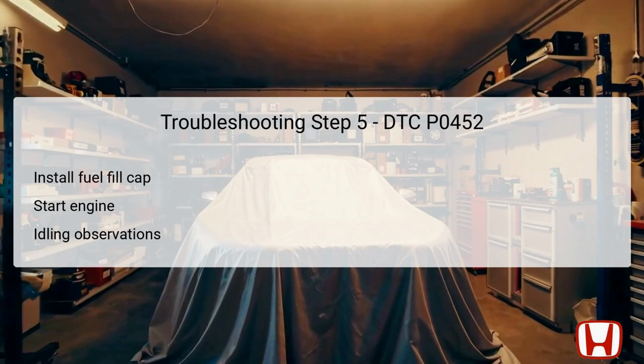The purpose of this step is to observe if the previously triggered error code reappears, providing insight into whether the FTP sensor circuitry is consistently underperforming. Any further anomalous statuses should be noted and acted upon based on HDS readings.